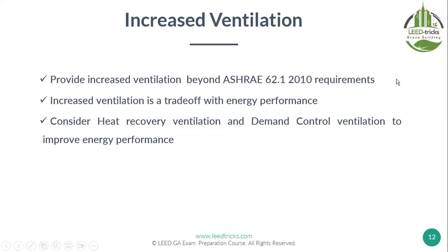So we'll speak about that now, this issue. If I want better indoor air quality, the issue is that this air comes from outdoors. The more air you bring, the more cooling or heating you need, so it will be a problem for energy. Increased ventilation is a trade-off with energy performance, meaning if you increase the ventilation, energy will also increase. So this is an issue. You want to increase ventilation, but you don't want to increase energy.